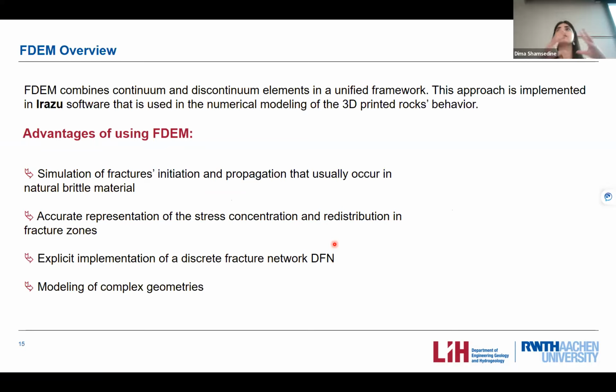The simulation starts with a continuum entity or a set of continuum entities, and as it progresses, these entities undergo elastic deformation, translation, rotation, and can fracture and form new separate discrete entities. So we can see the clear transition from a continuum media to discontinuum media.